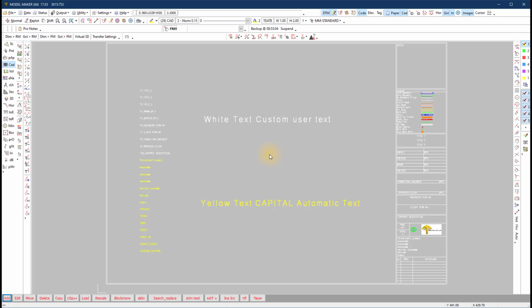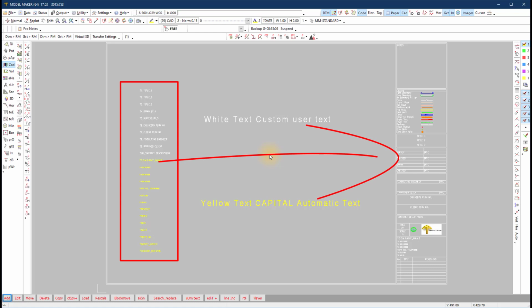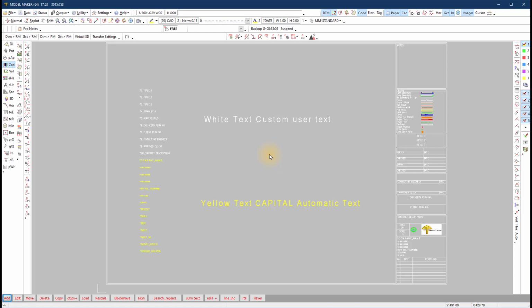The CAD text from the pattern will help you to know how to define the special title block layers. Use the CAD text as an example. Copy and paste, edit or move them into the title block area as you need them. Edit the text to be the color and size you need. And when you finish, delete the ones you do not use or need.